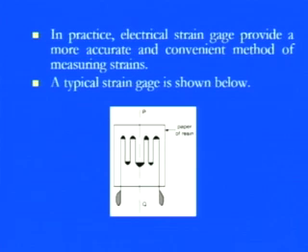So, here we have an electrical strain gauge. It is simply paper or resin in which there are two segments. Here, this is simply a block PQ, and this is the center line. If we apply any kind of distortion, there is a change of potential, like a change in a potentiometer. If that small change is amplified, it will give you a clear picture of what exactly the distortion or deviation in the element is. So, electrical strain gauges are always based on the change of potential or voltage within those elements.